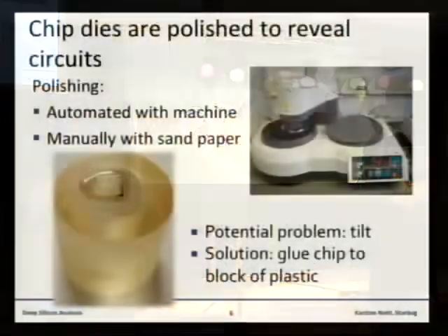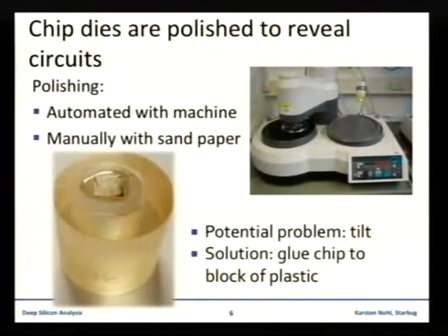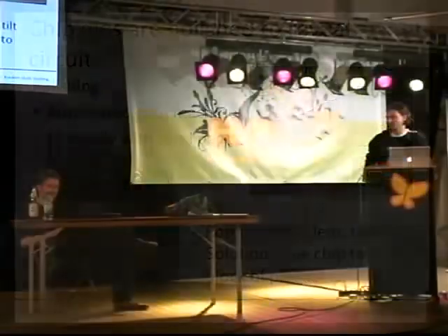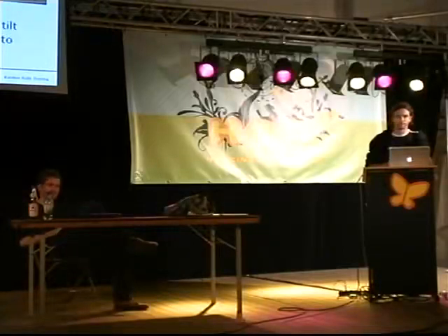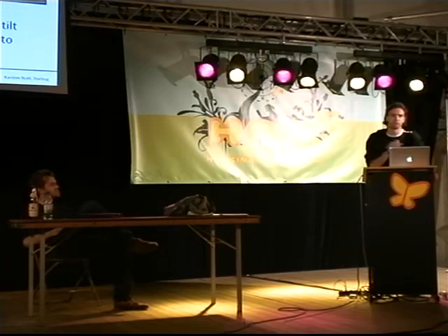Let's point out, though, that this polishing machine is absolutely not necessary. Nice to have, but we have been doing fine with the finest sandpaper and a vibrating surface at my university. So this is deluxe equipment. You can definitely do with less fancy stuff. We started with polishing equipment from an optical fiber laboratory. So everything below 1 micron grain size of the polishing liquid or polishing paper should be fine.